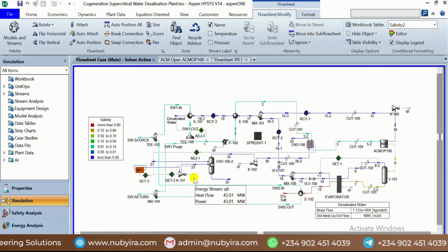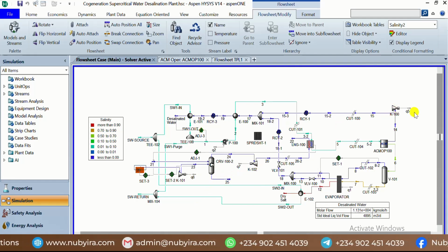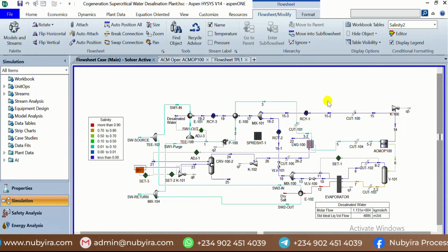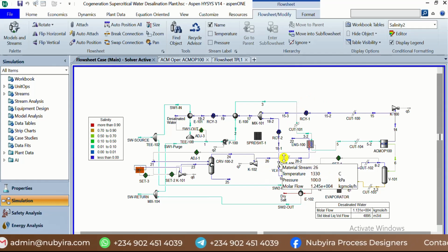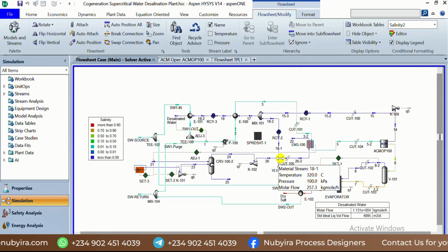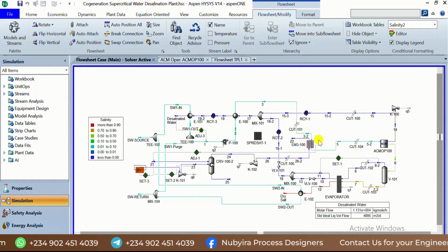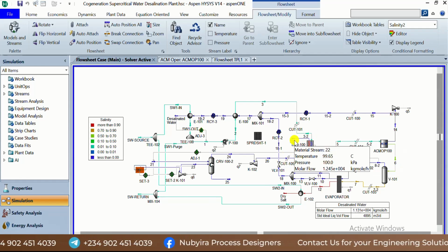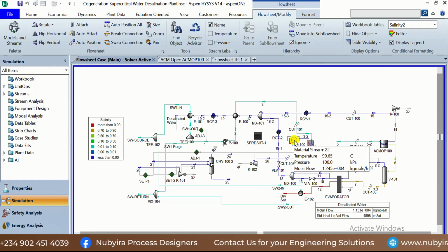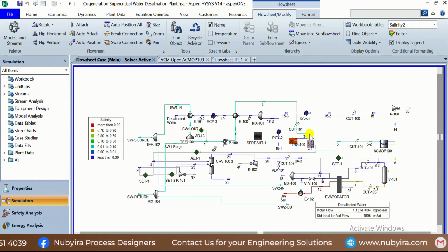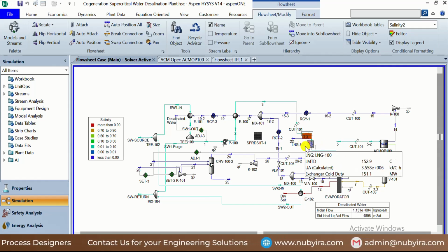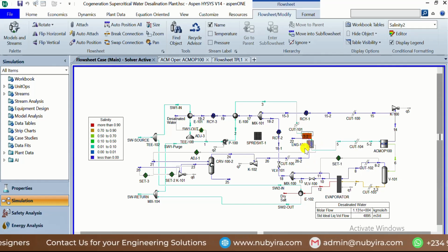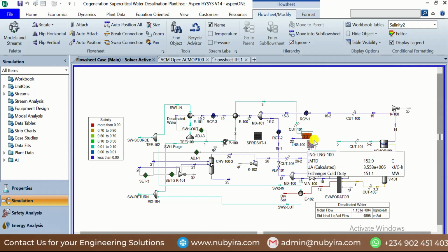This is for 3 megawatts. So the net will be added to this steam turbine to produce the total power from the power plant. And the flue gas from the gas turbine is used to drive the desalination plant, and it's sufficient to drive it. You can see this 99.65, and this is greater than the inlet temperature of the plant, with a 5-degree minimum temperature approach for safety reasons.